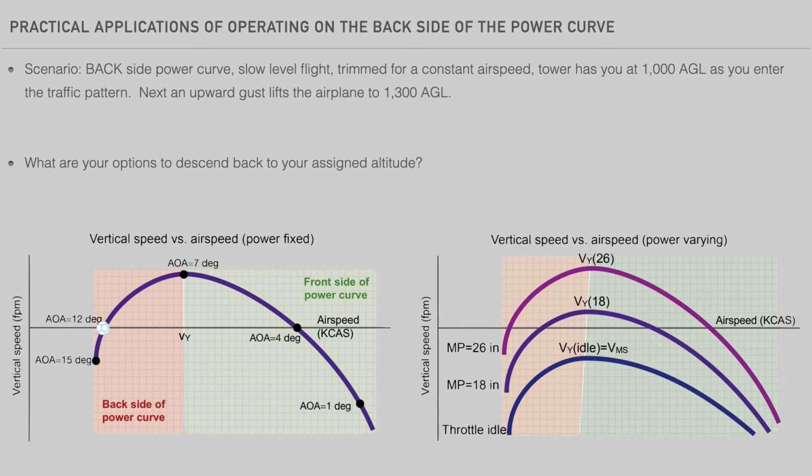Well, if you pull back on the yoke to increase the angle of attack, the airplane would slow and begin a descent. However, you are near to the ground and close to the critical angle of attack and risk a stall. Alternatively, you could pitch forward, which would result in a descent, but you would also be accelerating toward the ground in a nose-low attitude. Pretty scary.